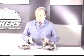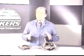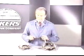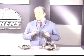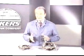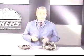Reversing oil flow to and from the motor would, of course, cause it to rotate in the opposite direction. Now that we have an understanding of how the pump and motor operate as individual units, let's try putting them together. If we could interconnect the ports of our cutaway units, we'd see that by merely moving the pump's lever control, we could drive our motor fast or slow in either direction.